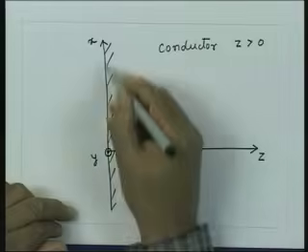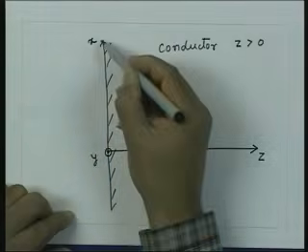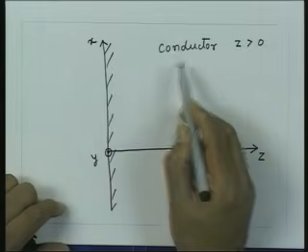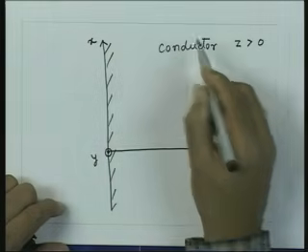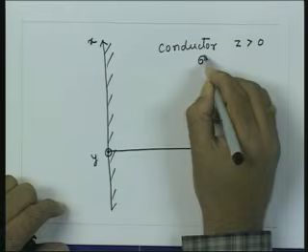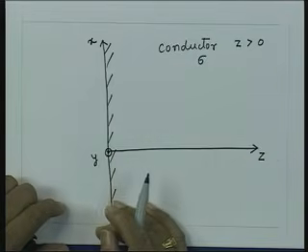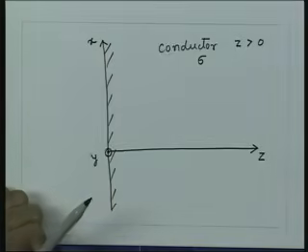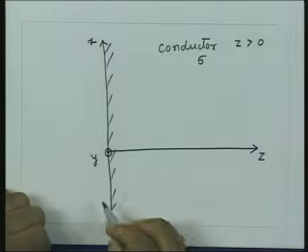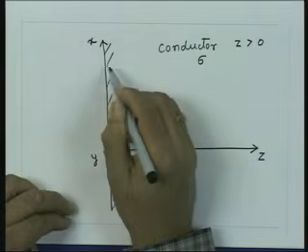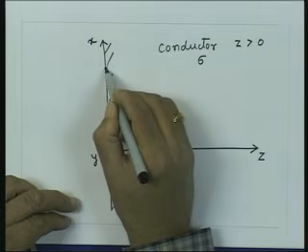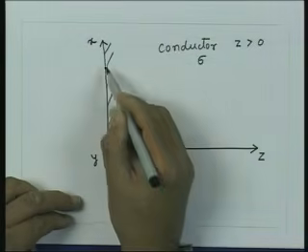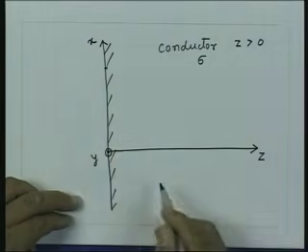Now if I have some electric field at the surface of the conductor, note here, since the conductivity is not infinite, this is not an ideal conductor; I have a conductivity for this conductor which is given by sigma. So the tangential component of electric field is not 0 now, because the conductivity is not infinite. So let us say I have a certain value of electric field in this direction, and that electric field essentially will exponentially die down.